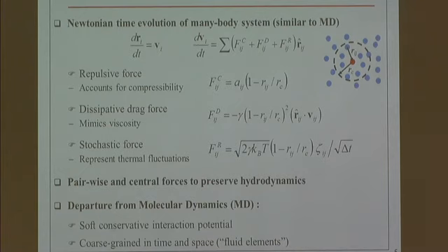by the fluctuation-dissipation theorem. And the important thing about the DPD, which is actually what makes it very useful for our applications, is that all these forces are pairwise, meaning that all forces always act on two particles, right? So what it gives us is that the momentum in the system is exactly conserved, right? So if momentum is conserved, this system will always reproduce hydrodynamic behavior, even if we have a relatively small number of molecules or particles in the system, right?